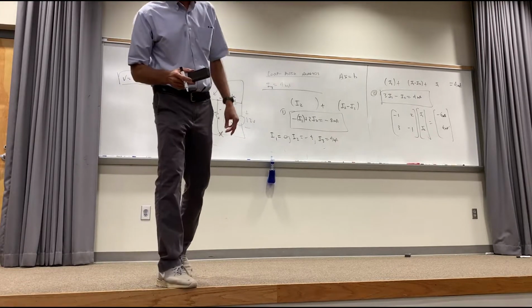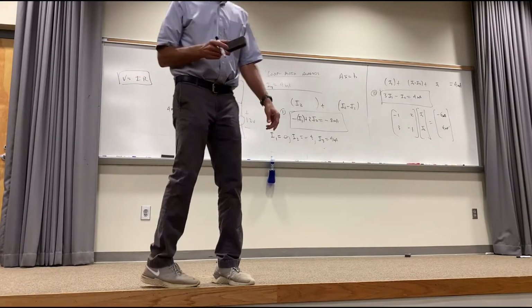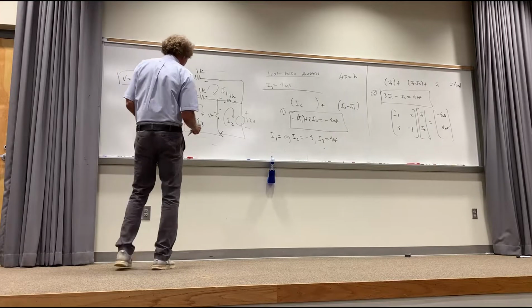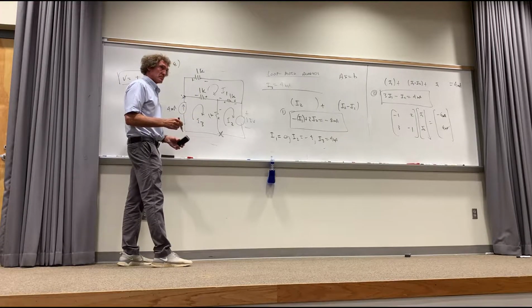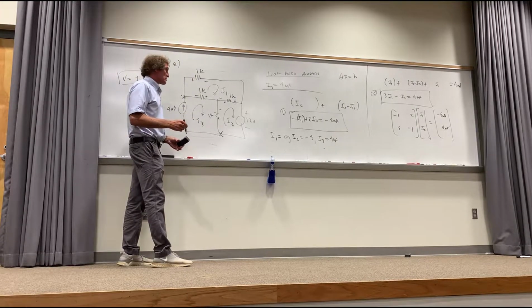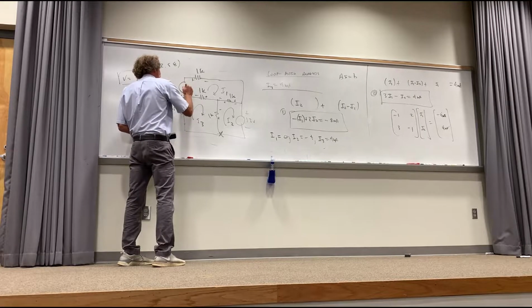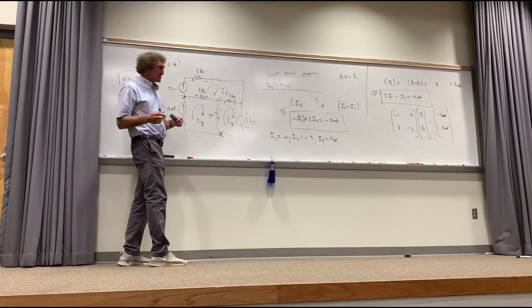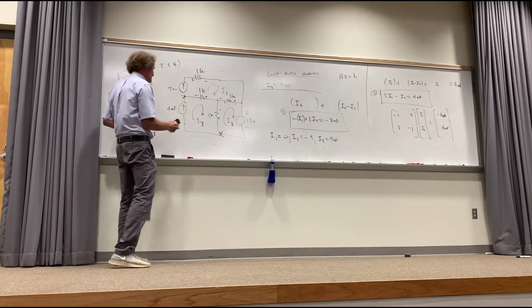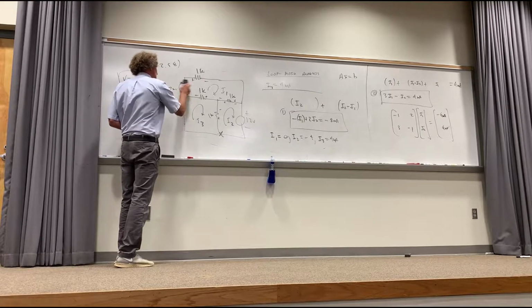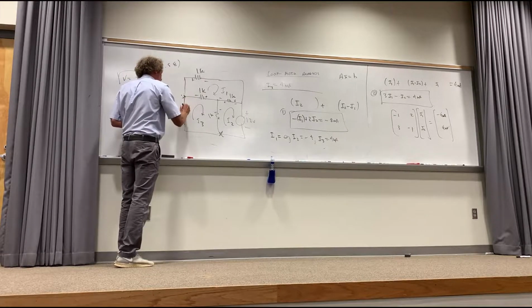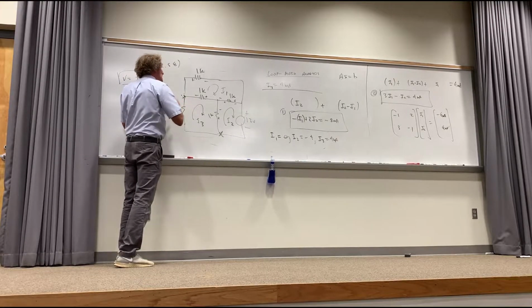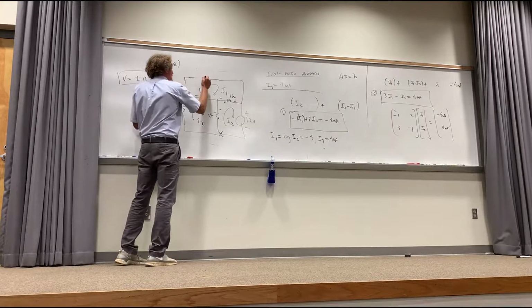You're saying we know I3 because of the 4 milliamp input, but what would happen if we have an amp input on multiple loops? Would it define both of them? Well, it's even better. If I put this as like 2 milliamps, now you know I1. Well, I mean, if you swap the 4 milliamp for the 1 ohm resistor on the top end by I3, and it's part of both. That's not a problem. Here, let's do it. Let's put 1K down here. Let's swap that and make it 4 milliamp.